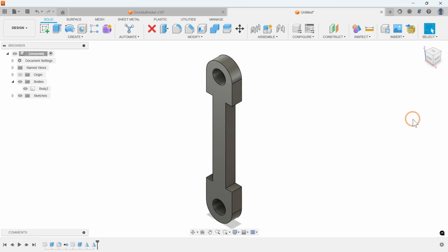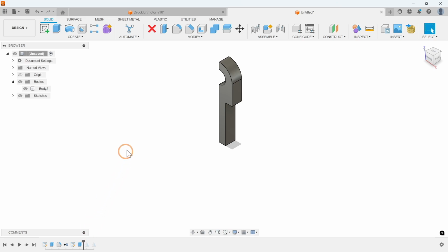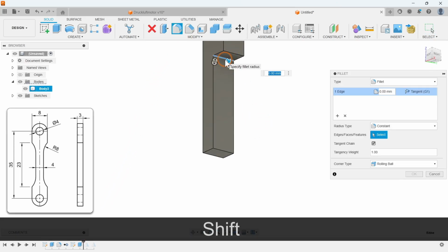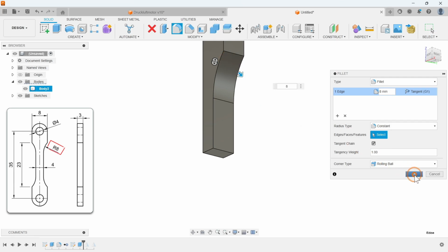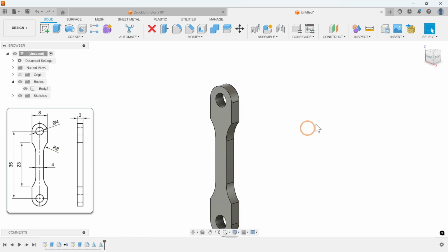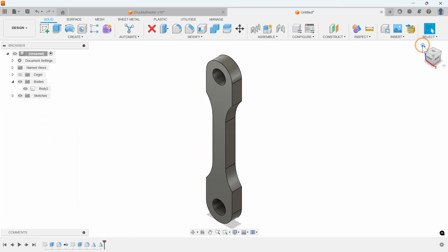We could now round off the four inner edges of the connecting rod. Alternatively, we can move the transition marking behind the extrusion of the quarter body in the design process and add the rounding there. If we move the timeline marker back to the end, the filleting will automatically be integrated into the mirrors. We do not need to adjust the material of the component since it is made of steel.